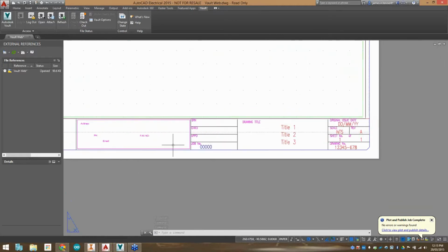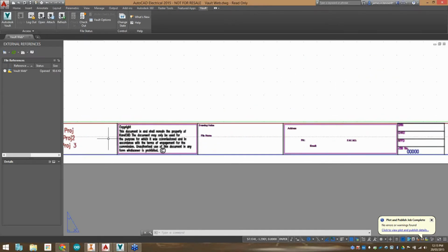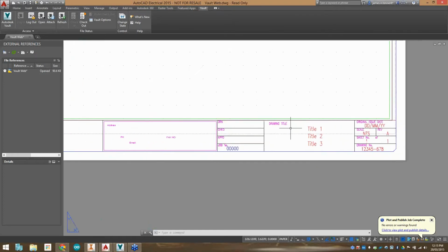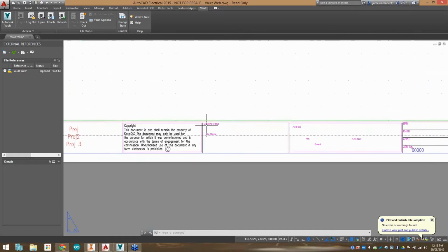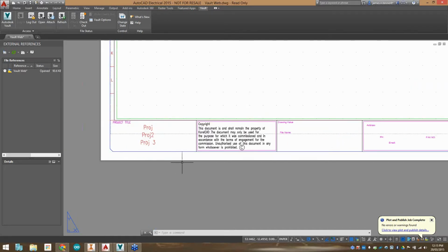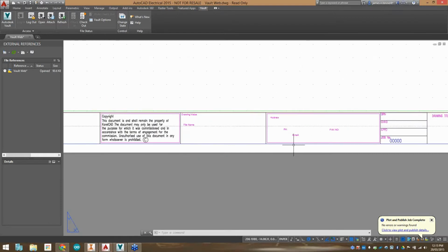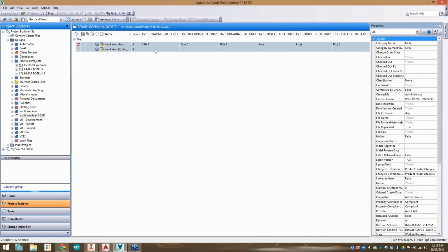So that right there is a way to save an amazing amount of time, especially when you need to make multiple changes in multiple drawing title blocks. It's extremely useful when editing hundreds of drawings at a time. So let's say in the situation where the address has changed and you need to update 1,000 drawings or something like that, for that Vault is extremely useful. So let's say we just wanted to do that and update the address on those 2 drawings.